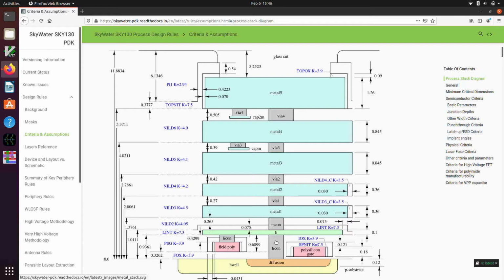And so if you can stay closer to the surface of the silicon, you're better off doing that in making your connections. I think when you're routing cells, you should try to stick with polysilicon and local interconnect for all of your local connections within a cell, and then maybe you have to go up to metal 1, but I would not go much above metal 1 in routing your cells. That way all the other metal layers are available for flying over top of the cells or making power distributions and stuff like that.